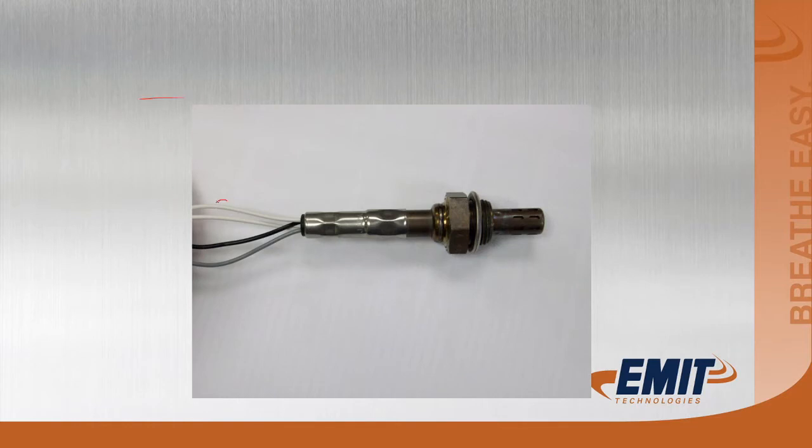Okay, so we have these two white wires right here. These two wires are 12 volt, and they're a PWM signal. We bump that current in a square wave, and the amount of heat we need is determined by the resistance. To warm that up, we only turn it on for a short period of time, and then turn it back on and back off, back on, back off. The more heat we need, the longer we leave it on. The less heat we need, the shorter time that it's left on. Again, that's 12 volt. There's no common ground, so they're not polarity sensitive on those two wires.